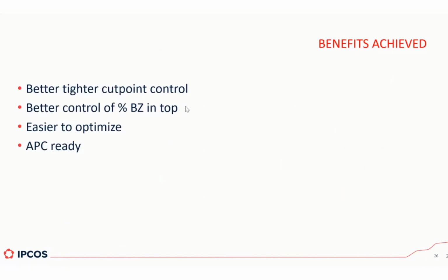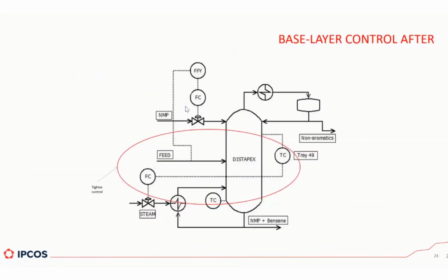Just let me show you here. Anyway, that was in the previous one. Just wanted to refer to you. So they wanted to control the top temperature, the sensitive tray in the top of the column, with the solvent. That didn't work really well. Did not work at all, actually, because again, the job of the solvent is not exactly the same as a reflux.